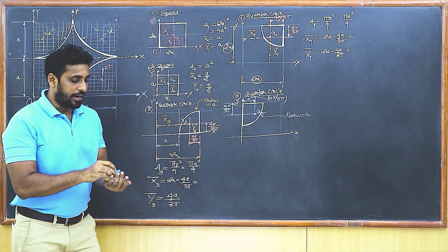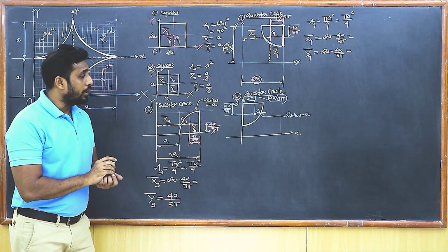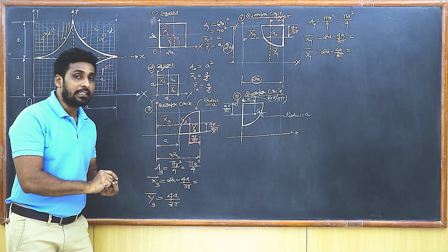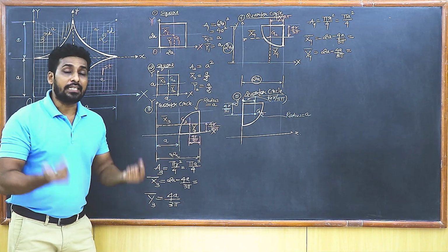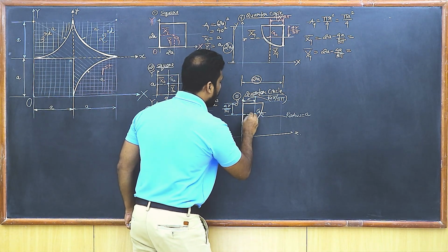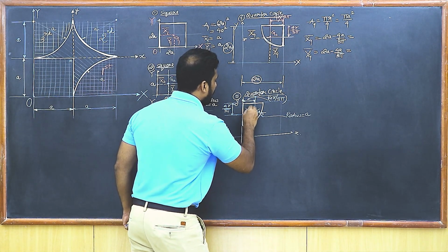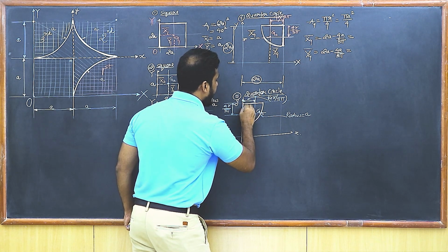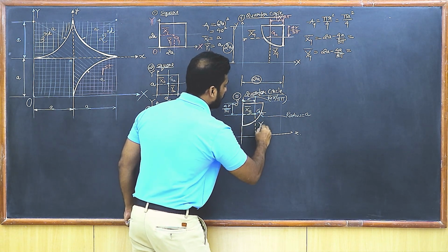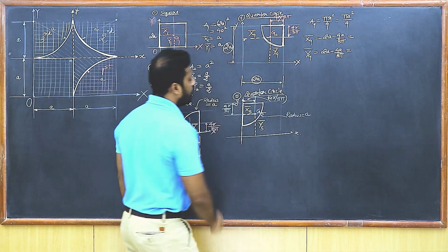That's the centroid G5. Now, you need to again tell me the distance of the centroid from the original y-axis and x-axis. It becomes x bar and y bar. So, if you observe, this is G5. I draw the horizontal distance here. This is going to be x5 bar, and the vertical distance is going to be y5 bar.